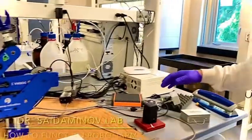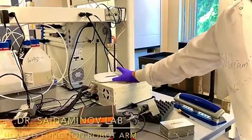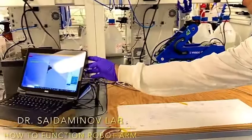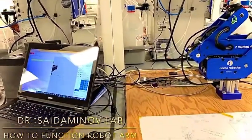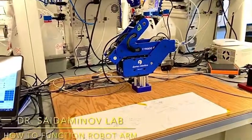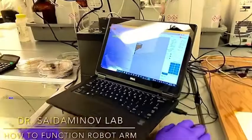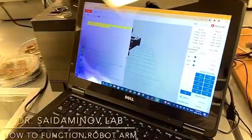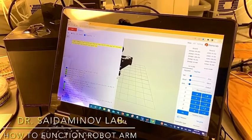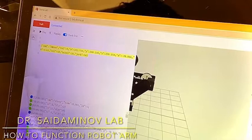So once we want to work with the robot arm, we need to turn this on and have internet, and this internet should be connected to the laptop that we are going to use to deal with the robot arm. Then we need to open Chrome, go to the Dorna Lab, and refresh it. Once it says it's connected, it means it's ready and good to go.